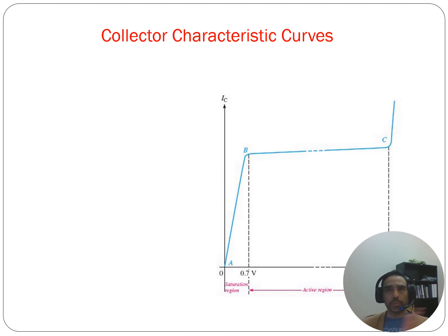Yeah, I sub C is proportional to I sub B. How do we identify that in the curve? The active region is where I sub C increases linearly with I sub B, and the collector-emitter voltage VCE is moderately high. So it appears as a slope on the curve, and it shows I sub C versus VCE for different I sub B levels. I'll show you another graph that actually shows many different I sub B levels.